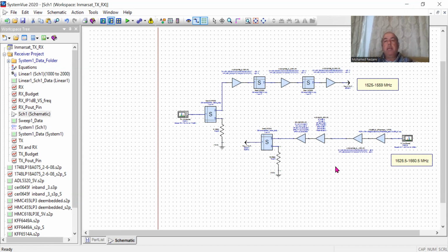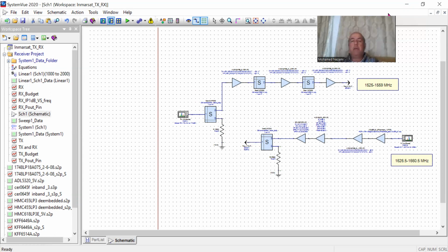So what I did is I put the design using the tool from Agilent, and we have the receive path in here and the transmit path in here. And the BGAN terminals share the same antenna, or aperture antenna. And so we have to have a diplexer, a very high Q pre-selective diplexer, which splits off between the receive and transmit, because as you know, they both have to be spectrally isolated, separated.